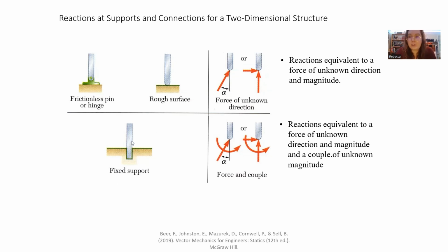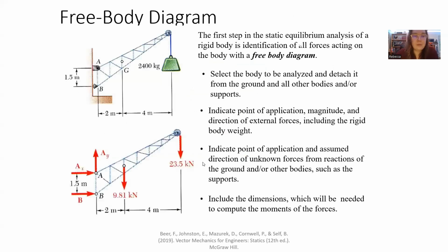Our fixed support, picture like a beam in a concrete base that is somewhat submerged for a little bit, and that adds that fixed support at the bottom. It doesn't allow any motion. It doesn't allow you to slide it, and it doesn't allow you to rotate it freely. And so we're going to add a force in our positive X direction, our positive Y direction, and we're going to add a moment anywhere we break a fixed support as well.